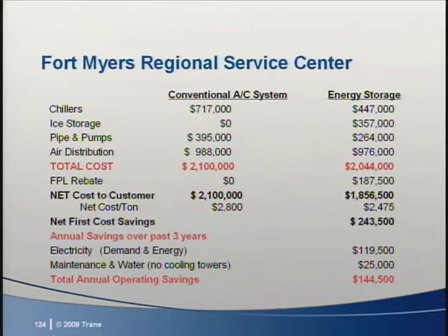Air distribution costs were essentially the same, and savings came from right-sizing the ICE energy storage system with smaller chillers and electrical equipment, and using an aggressive low-flow delta T chilled water distribution system. In your handouts, you'll find an ICE energy storage project data sheet. We created this to accompany this broadcast. We hope it will be helpful in reminding all of us the key design considerations. Let's move on and have Susanna get some of the details of the economics.